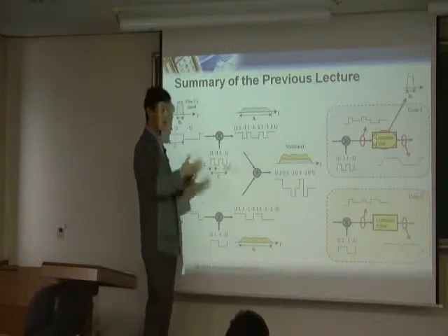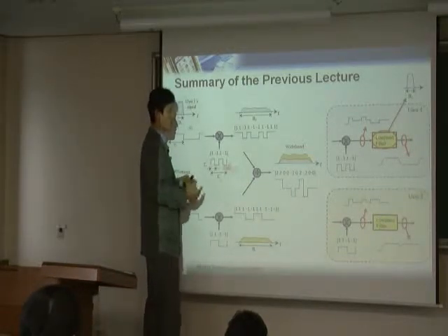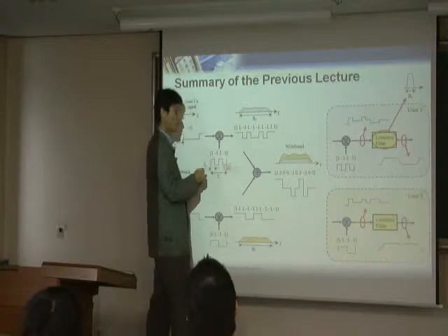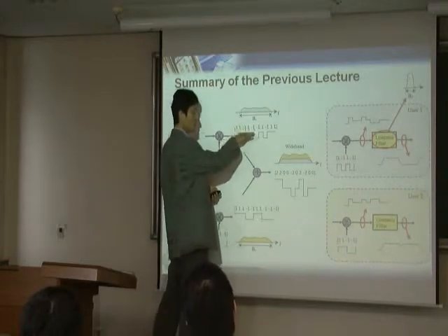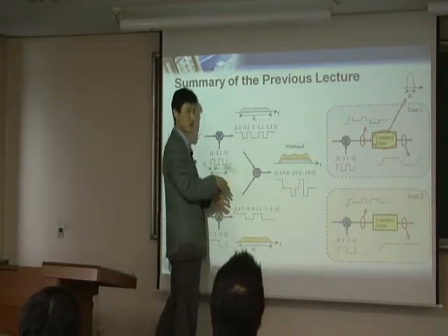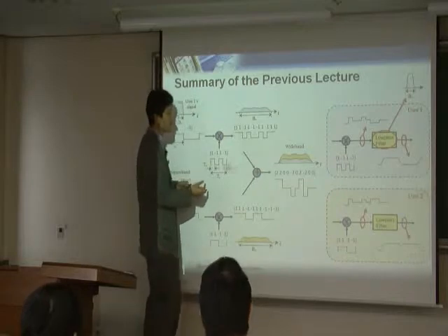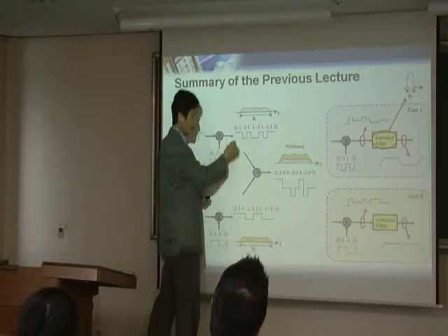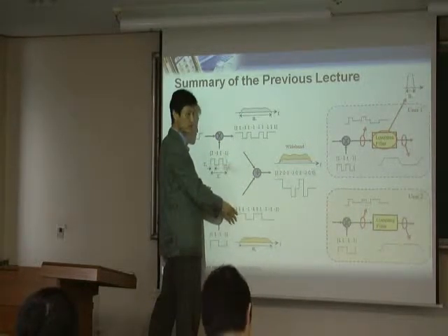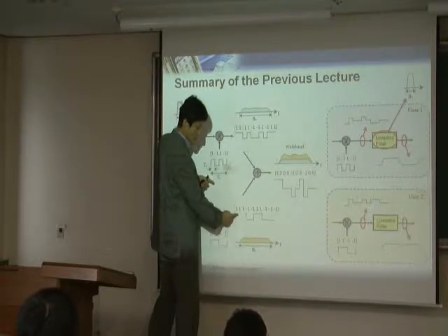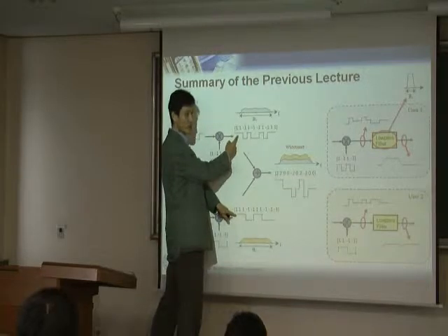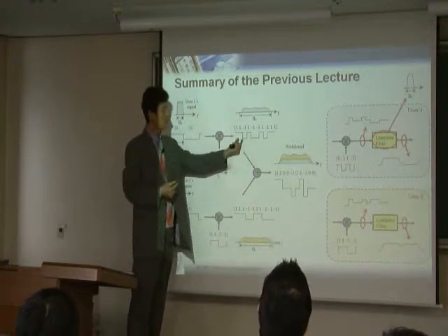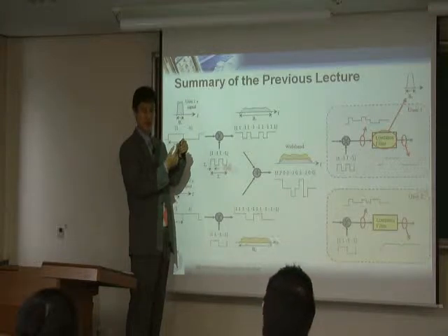But what is likely in the actual scenario is that we try to make a synchronization, of course. We always try to make them synchronized. But what is actually happening in reality is that because of some unexpected environment, there is always fading, some multipath, some delay. What is likely is that this bit is partially overlapped, partially asynchronous with the other one. Their symbol boundary does not match exactly. Maybe it's a little bit off from the symbol boundary. So in that case, the offset is less than one chip, but still there's an offset. You know what I'm saying?